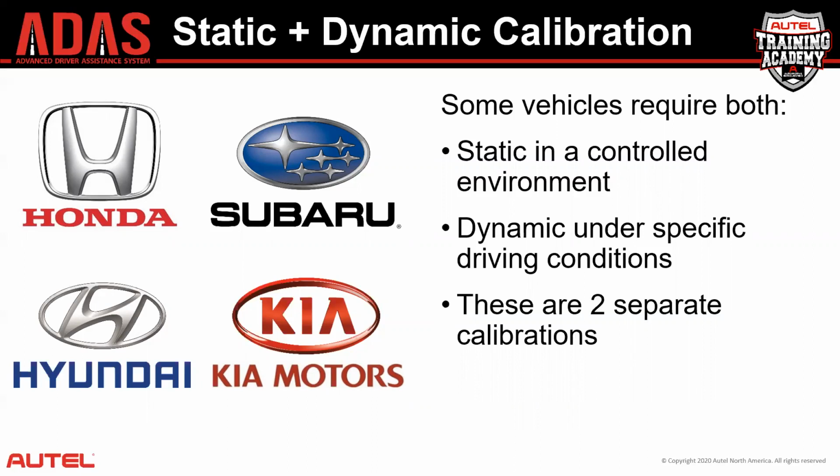Subarus, Hyundais, Kias, some models will actually have the same thing, a static calibration followed by what they may call a test drive. But if you read the instructions, that test drive tells you how to drive the vehicle and the driving conditions that it's looking for. That is a dynamic calibration. That is a separate calibration from static.